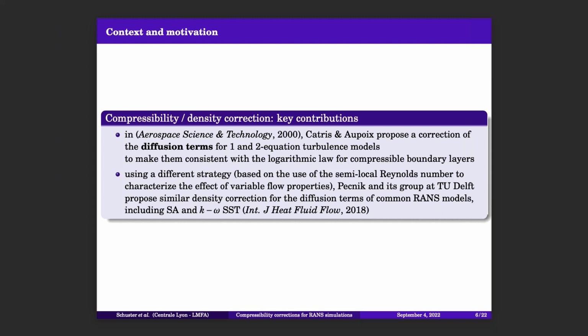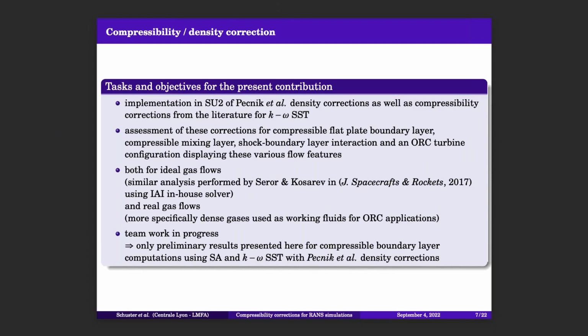Next slide, please. So the tasks and objectives of the present contribution are the following one. First, we want to implement in SU2 this Pecnik et al. density correction, as well as compressibility correction from the literature for K omega SST.